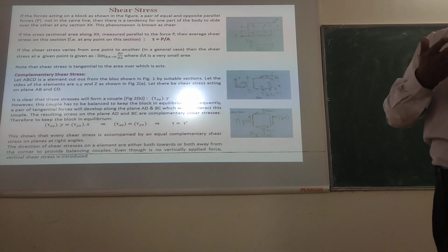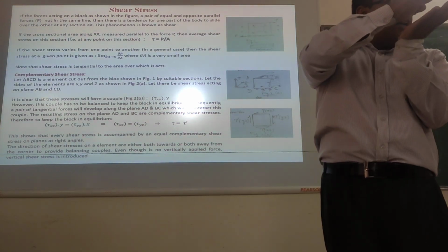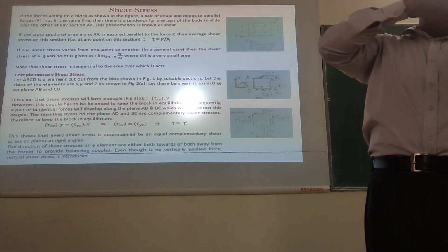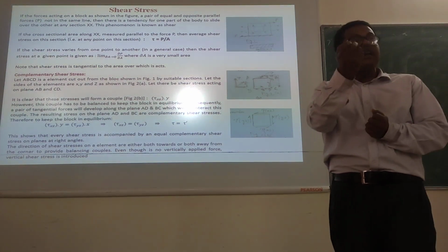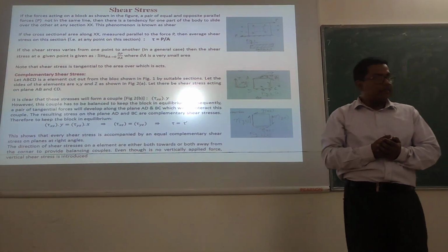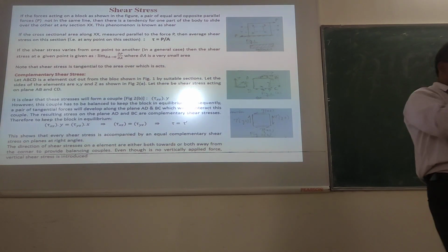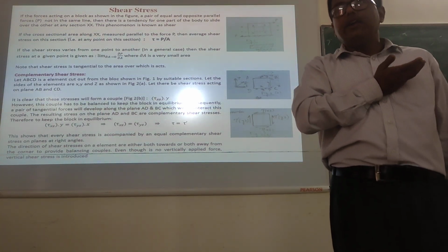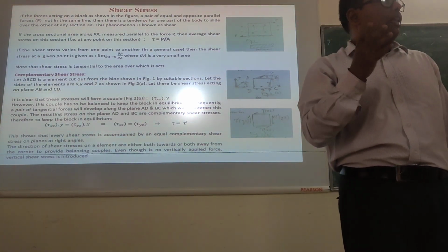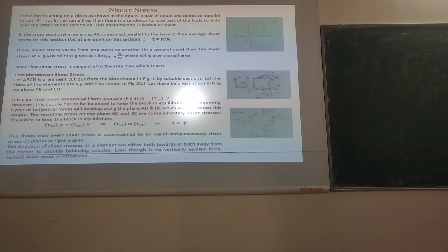So internally, when the push is there, when the sliding intention is there, at that time there will be an internal resistive force also generated. And when we get that internal resistive force, if we divide it by the area on which that resistive force is acting, we will get the stress. And that stress will be termed as shear stress.